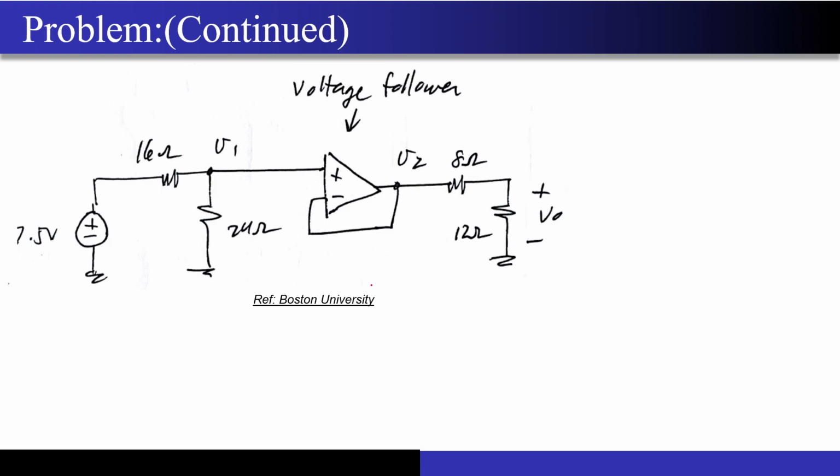Correct. So now let's try to solve this particular question. What is this block over here? By the way, all the op-amps will be ideal in all the questions that I will be solving right now. Ideal op-amp means you can apply virtual ground, you can assume that there is an infinite gain present in the amplifier. There are no offset voltages, nothing. So how to solve this question?